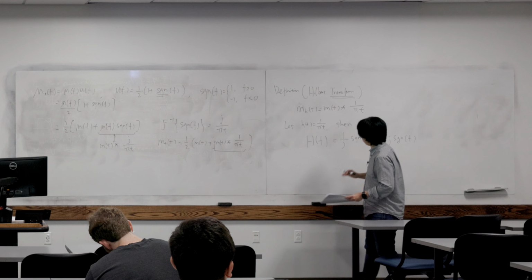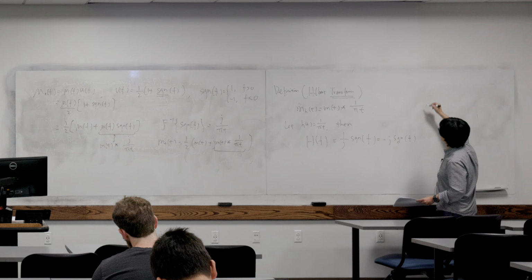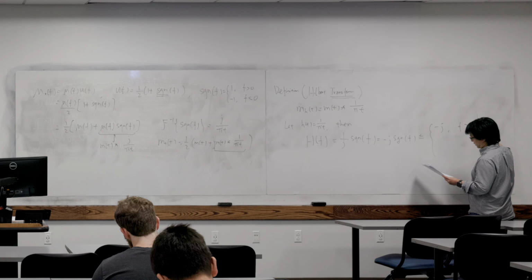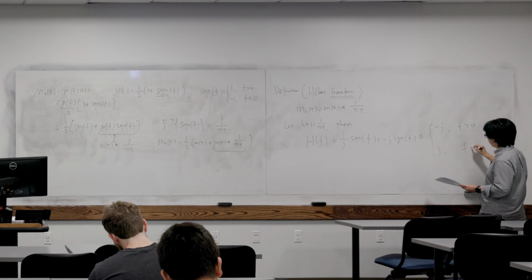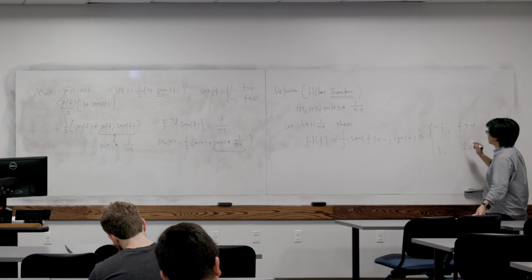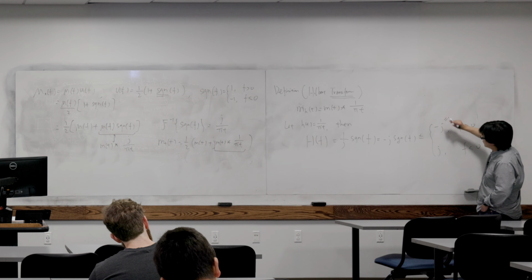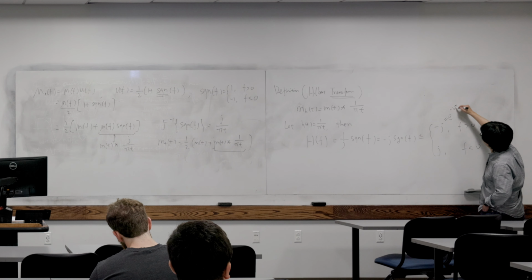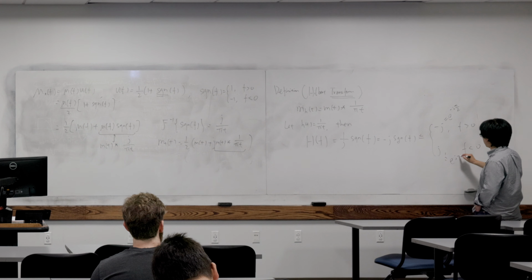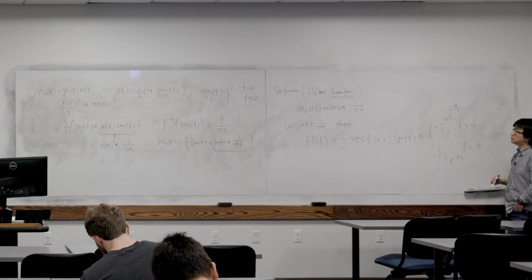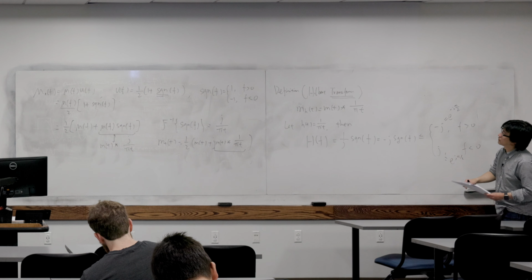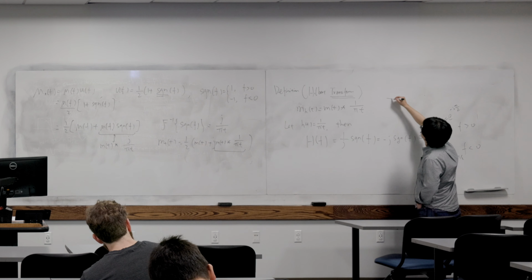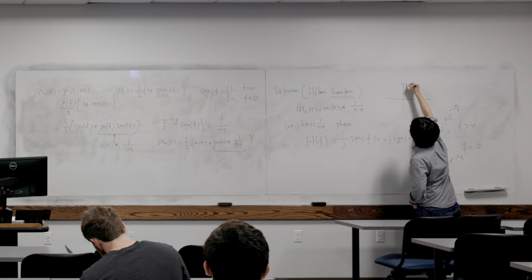And if we write this sign down, it means that H of f equals minus j when f is bigger than 0, and it is j when f is less than 0, right? And also, this minus j basically is a phase shift. So this equals e to the minus j pi over 2, and this equals e to the j pi over 2, right? If we sketch this guy, we can see the magnitude of H of f.